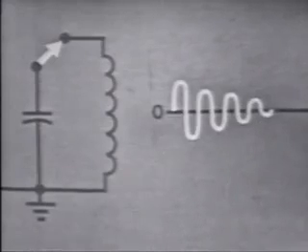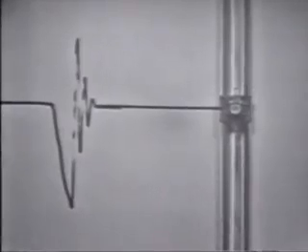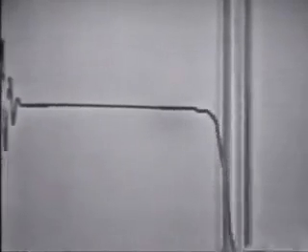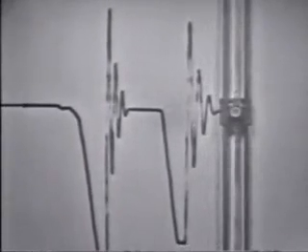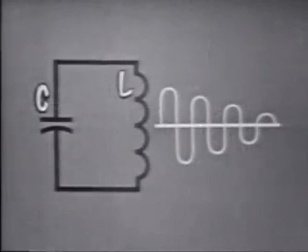The current waveform generated by the LC circuit looks very much like the graph of our mechanical oscillator. Why did the amplitude of the oscillations decrease? In the mechanical oscillator, inherent resistance or friction. Now, if we apply this reasoning to the LC circuit, it's obvious that the decrease in amplitude is caused by internal circuit resistance. That is, the resistance of the wire finally dissipates all of the energy.